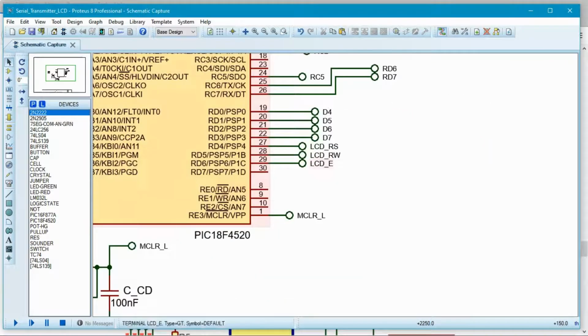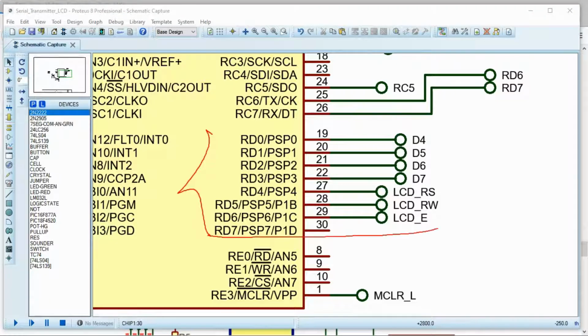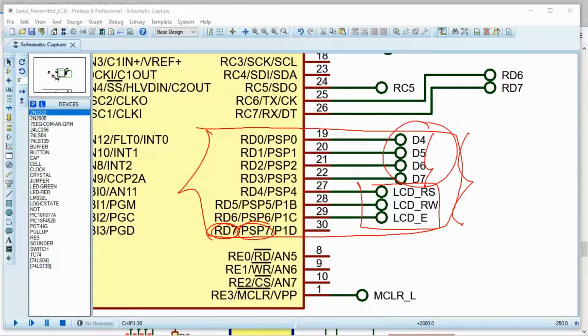That's the basic circuit, but now you see with some extra connections in the port D. So you see we are using the port D in some way, almost every single pin in this port. This one as well can be used later, the pin 7 if you like, to switch on and off the power supply of this device, but this is not implemented now. But you have 3 pins used for the handshaking signals and the other 4 used for the data. That is the way it works. Okay, and the names and everything is taken from the Microchip PIC development board and from the library. So you better do it as it is here. Do not make any modifications, because in some way this is given to you and that makes it simpler.